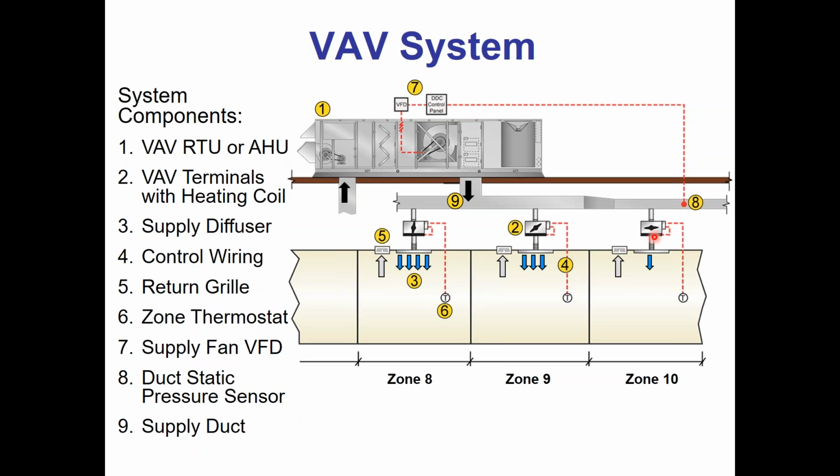That's very difficult for you to figure out where to put until the building's actually built. So normally what we do is we put that duct static pressure about 2/3 of the way down the duct. How we got the 2/3 number? It's just a wild guess, right? It's just a decent educated guess.